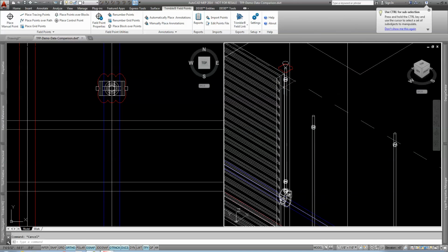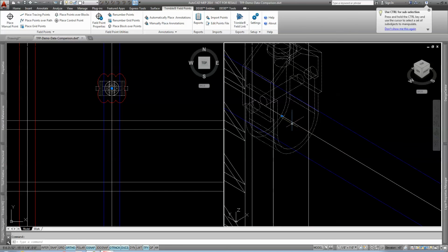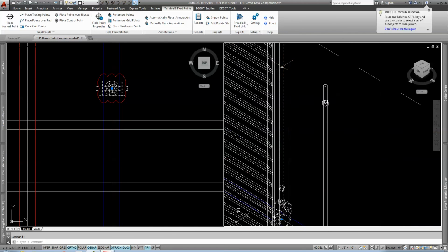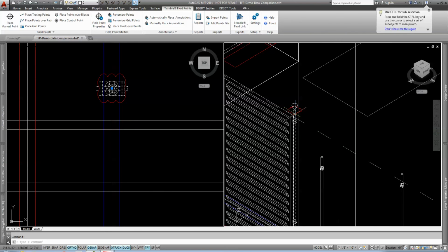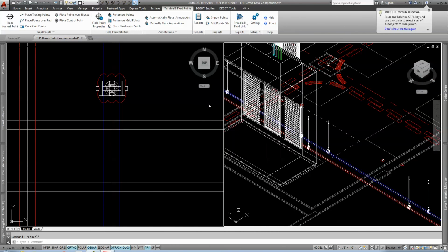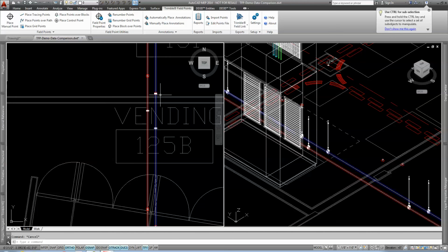This is based on how you make your blocks. My block, this is my insertion point. How do I know? I have a square right there. Okay, that's how you know where your insertion point is. It's wherever that little square is. If my insertion point was that top piece, then it would have come in properly. Okay, so there's a lot of different things you can do on here, and that's a very nice use because you can place your points ahead of time and then throw in your blocks for your hangers. You can do this for sleeves, you can do it for lots of different things.